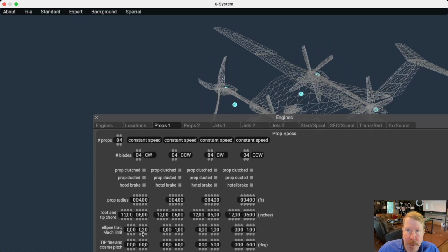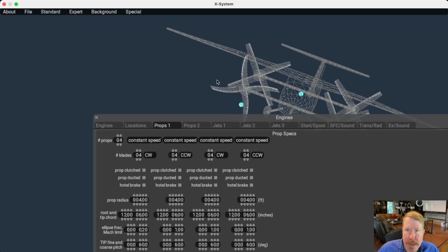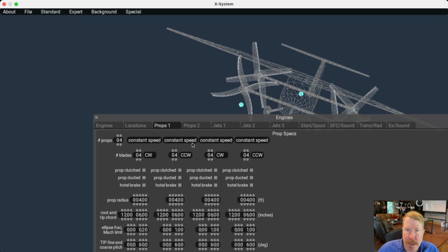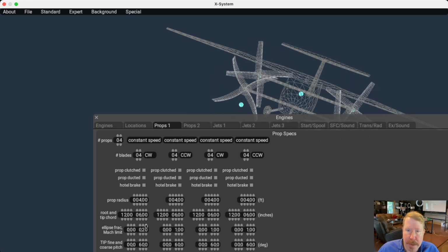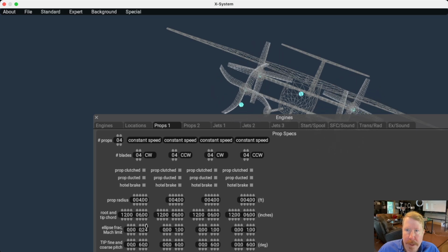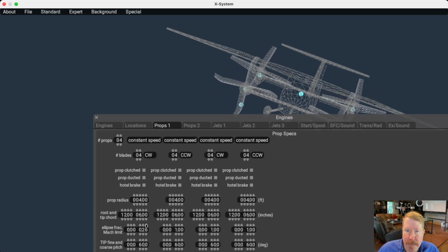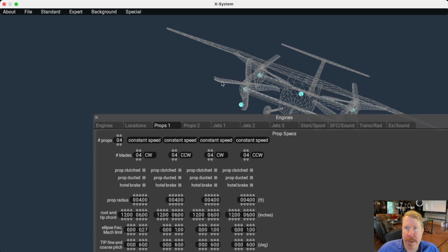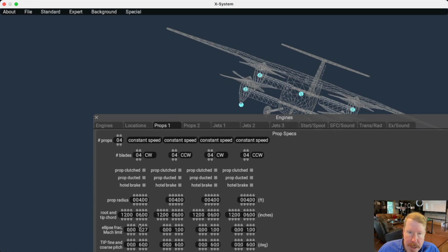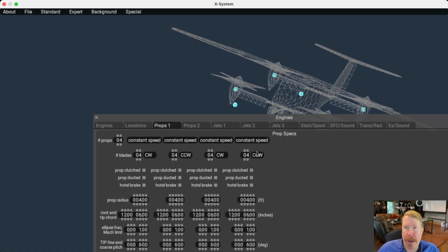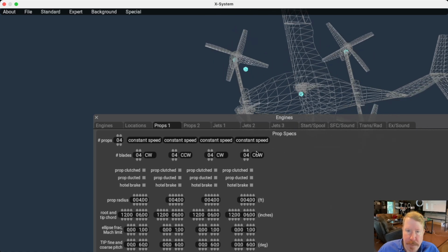Yeah, so if I had more RPM and speed, we would see the tips sweep back a little sooner. Oh, here we go. Now we're starting to see it. If I set it to about 0.27, you can see the tips are sweeping back to try and hold a Mach number. Normally we just enter 1 if there's no prop tip sweep at all.